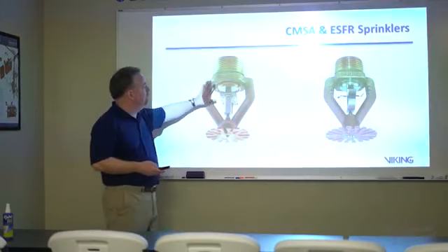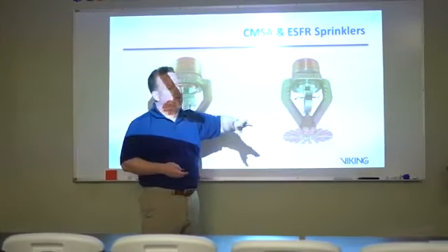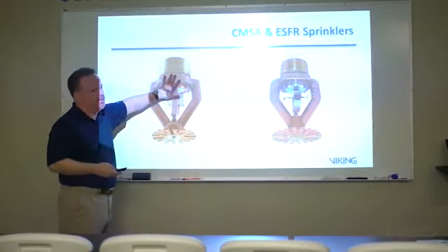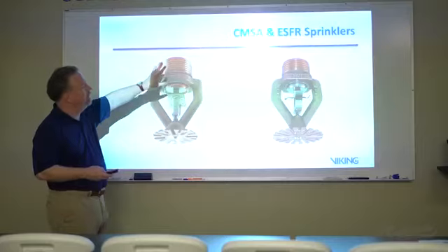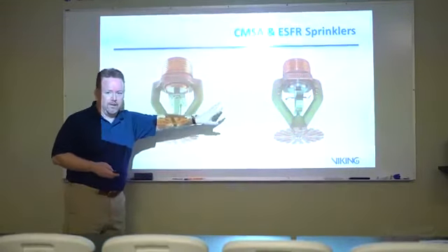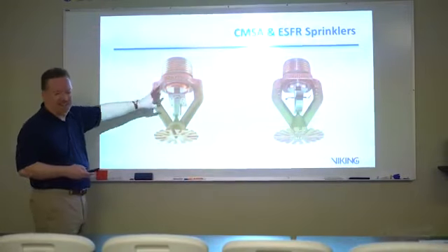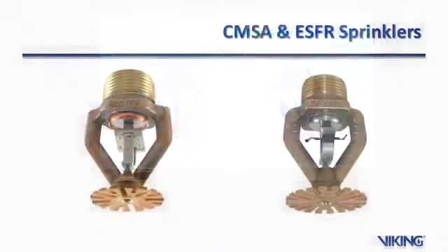Then we get into CMSA and ESFR sprinklers. CMSA is control mode specific application, and that's an ESFR. Do they look the same? They kind of look the same. It's hard to tell the differences between them sometimes. You have to take a look at the deflector to find out what it is.